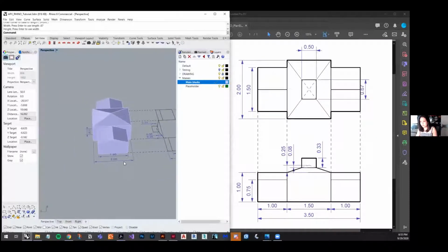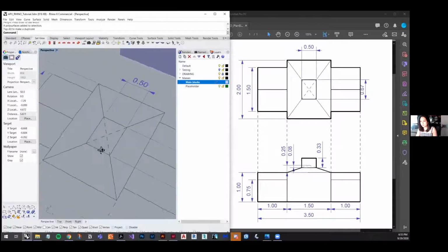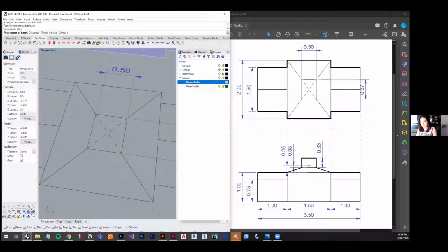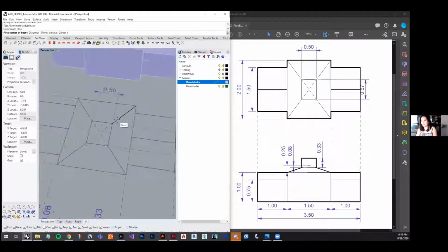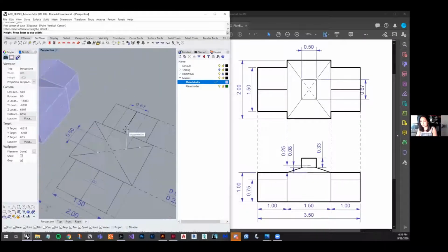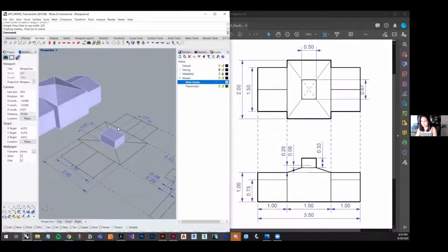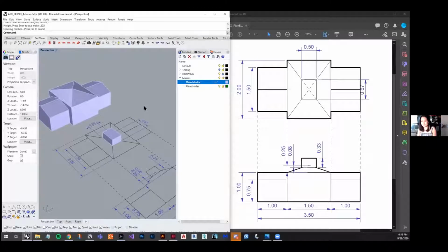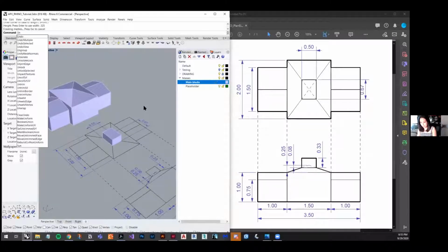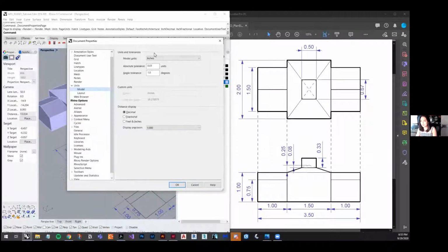whenever you guys are showing exact numbers, I like being more exact with my things. If I did 0.67, it wouldn't be exact with the dimensions of it. So I just like going based off of the drawing and building off of that. And so the height, it says 0.33, but I know it as 0.325. And so that's one thing to remember about your units. If you want to change your units, if you're in millimeters or something, you just literally type units and it'll pull up your preferences here.